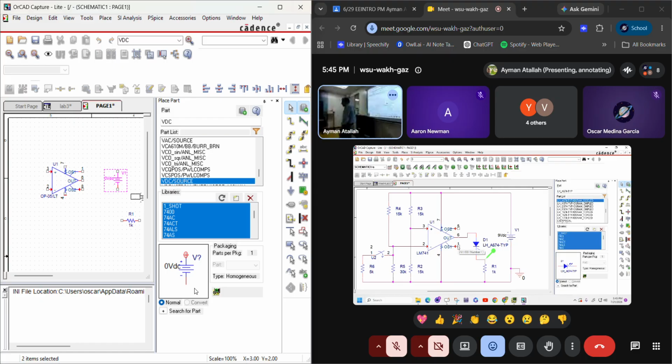Let me see. You have the same issue? Yeah. Okay. Remember, when you have a dot here, this means that you have a short circuit input. So it's important to delete the lines and take it. Make sure there is no dot. You have the same issue here. Okay. So it's important that when you have no dot here, like this one, it means that these 2 wires are not electrically connected. It's over each other, but not electrically connected.